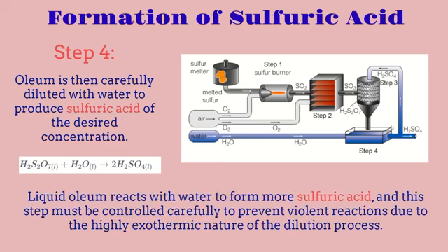So liquid oleum in this case reacts with water to form more sulfuric acid, and this step must be controlled carefully to prevent violent reactions due to the highly exothermic nature of the dissolution process. So in this case, there also has to be really good safe handling because this has a really high exothermic nature.